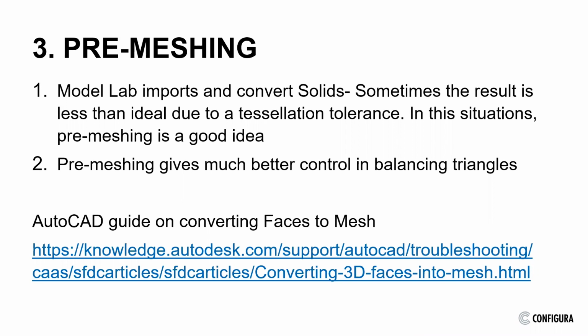Tessellation basically means how do you want to convert the solid faces into triangles, into vertexes, into the polygons. So if you were to pre-mesh it before you import it into Model Lab, it will stay the same number.